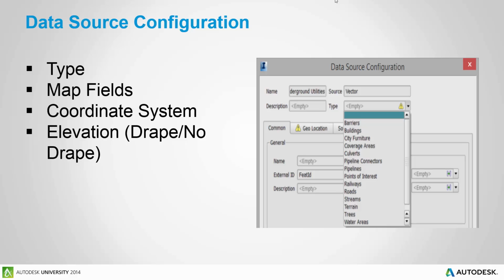You know, the digital elevation models will come in at the correct elevation, but other information you might want to drape on top of that digital elevation model. So, for instance, building footprints, you can bring that in and have it drape right on the model. That way your buildings end up at an elevation, where most building footprints are usually at elevation 0.